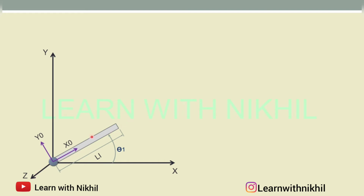This is the first link, this is the first joint. We have to find the DH parameters for this joint also, and as there are two links, for the next link, x1 is parallel with x0, y1 is parallel with y0, and again the z axis is coming outward. So the z axes are also parallel to each other at this particular point.